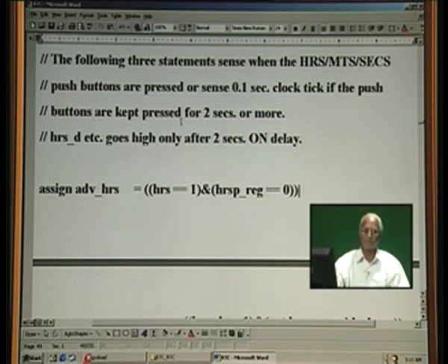This was the question addressed earlier by one of you last time. Every time we want to set something, we can go into auto mode, wherein the system looks for a key push button being pressed for 2 seconds, then it runs very fast, so that large delays can be easily set because it is running faster. If you close in, you can release the button and advance slowly by pressing the push button each time you want to count just 1, and that is what it means here.